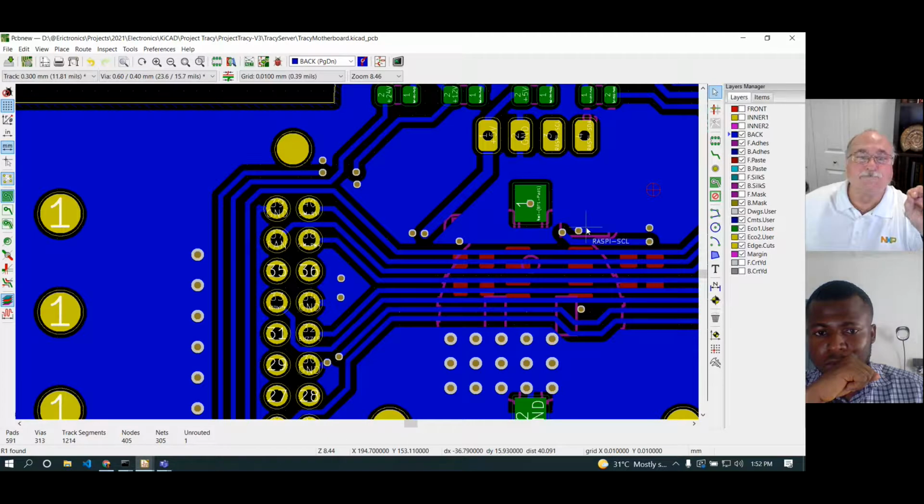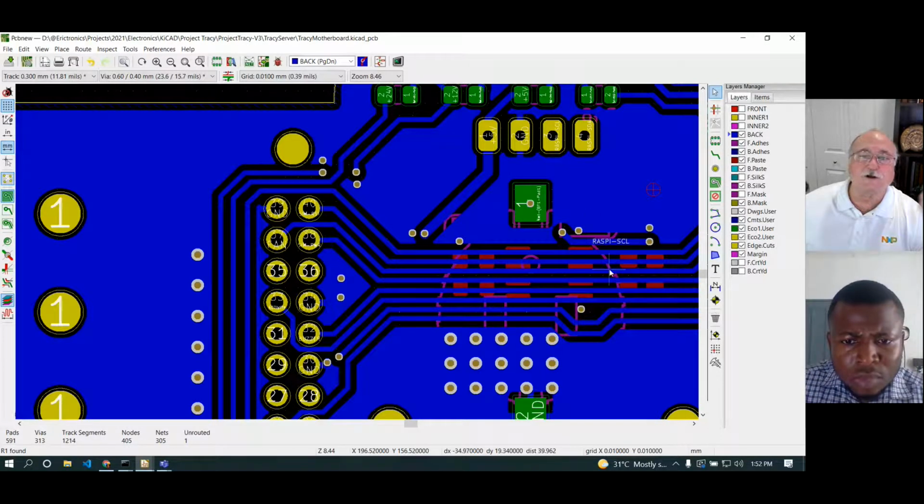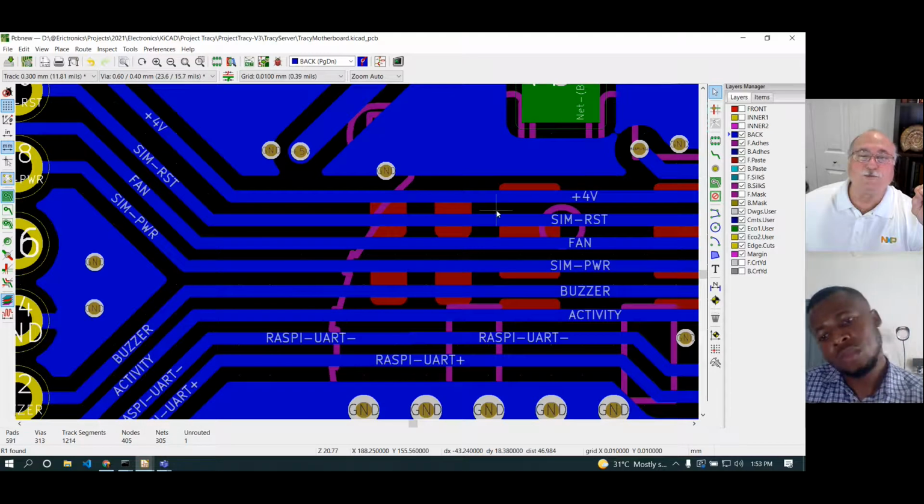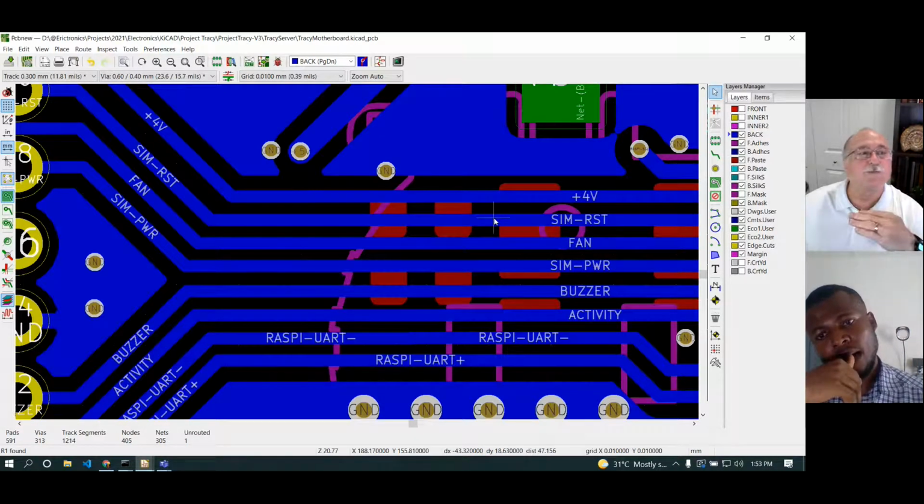But the magnetic field that it can create in a trace is much larger because it's physically smaller. So, for example, you've got an array of traces horizontally on the board. When a signal is moving through the top trace, it will induce a magnetic field in the trace next to it as the signal propagates down at the wavefront.